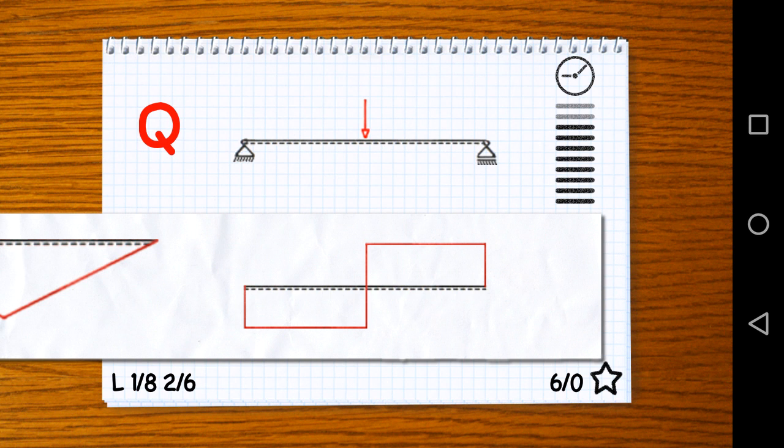Here, what's gonna happen when we look at the beam, our trick for the shear forces was to look at the beam from the right to the left, and we would have here a vertical force at the roller support going upward with half the value of the single load, of the external load, going upward. So we have a jump to the negative values, then the distribution stays constant because we have no distributed load, then it jumps back to the positive value, stays constant again, jumps back to 0 at the left support. Here's the answer.